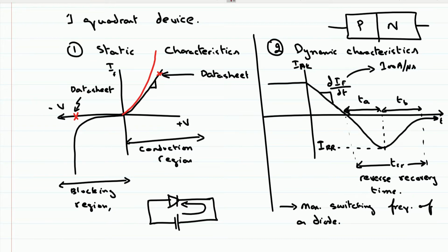This happens till we reach 0.25 of the peak current of the reverse recovery. After that, this current which is shown here is attributed as the reverse saturation current I0 of this given diode, because the reverse recovery current is there once a diode is turned off. So from the time we reach the peak value during a reverse recovery process to the time where the current becomes equal to 0.25 of the peak current, we consider that the diode is now turned off, and whatever current is flowing through that diode is attributed as the reverse saturation current.